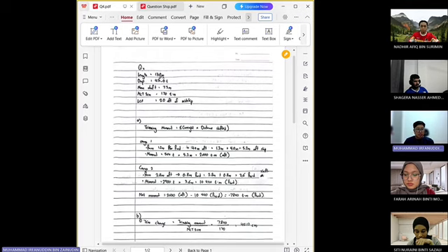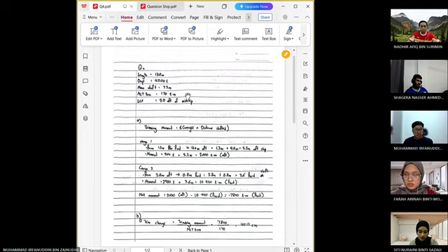First, we list out all the information given, which is the length of 130 meters, the displacement of 4,500 tons, with the mean draft of 7.5 meters, and the MCT 1 centimeter equals to 170, LCF 2.2 meter aft of the midship.